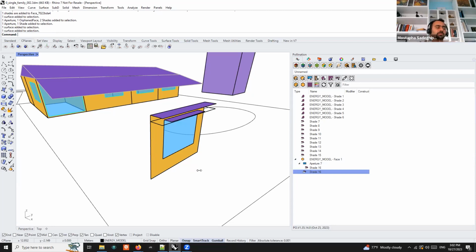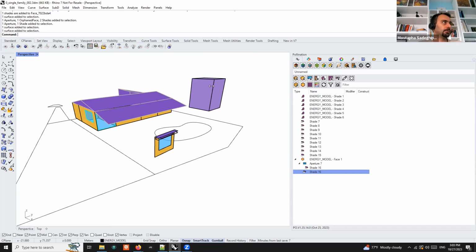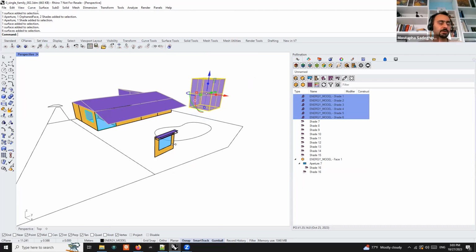Again, the reason we did this is that we develop a lot of very particular advanced workflows for companies who work on dynamic glass or window control. We need the apertures to know which aperture is part of the window and which is a generic aperture that is just in the model, so we can programmatically change, remove, or add them for the studies. For most of your use cases, you can just go with normal shade and it should be fine. Except, of course, if you go to IES, I would recommend modeling this as context shade and the rest as building shade.